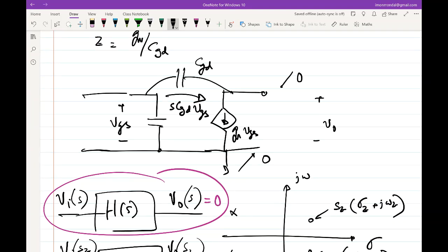Okay. Good question. So saying this is short circuited, but will that be the correct assumption? So let me ask you the question in another way. If you find any voltage in a network to be equal to 0, does that mean that it is physically shorted to ground?